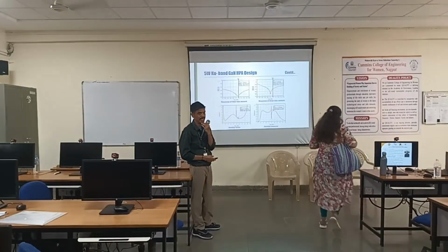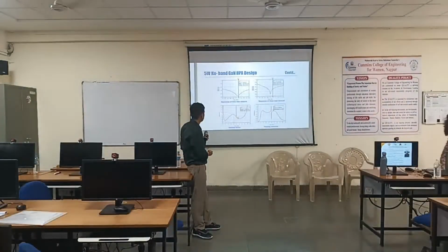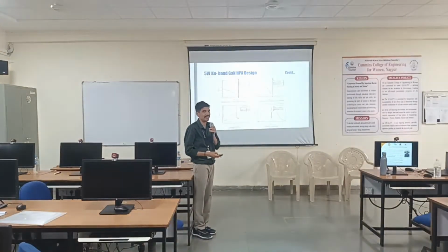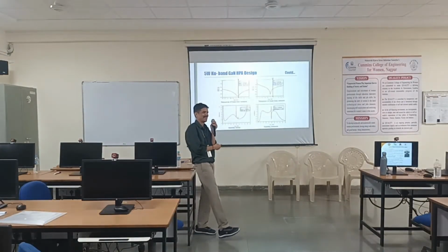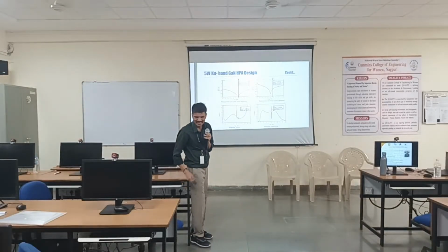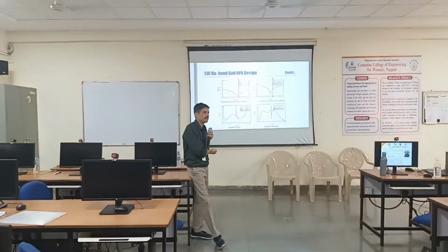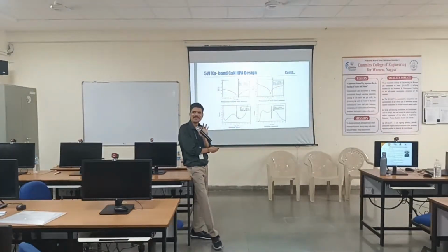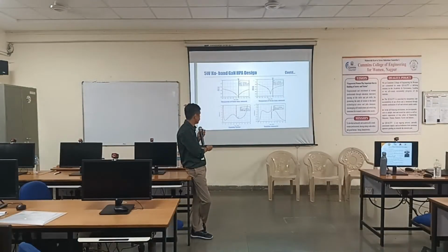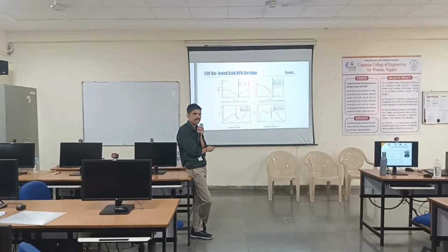Okay. So this is stability analysis. So the K and delta values, or stability factor, we can see should be greater than 1. Now please don't ask me why greater than 1. Otherwise I will go back and start talking about the Smith chart and all the stuff. So just a thumb rule: if the stability factor is greater than 1, it will not become an oscillator. It will become an amplifier only. So this is the gain what you can get, where it is S21. So the dB S21, dB S11, these are the results for the bias network. Bias network means the drain and gate side line.